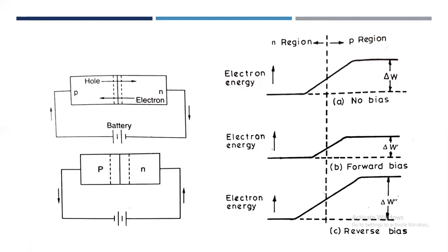For a given temperature, more of the majority carriers can now surmount this barrier energy than the higher barrier. At the same time, the number of intrinsic carriers that conduct the electricity in the opposite direction is unchanged, because the rate at which the intrinsic carriers are produced is determined by the breaking of covalent bonds, and it is not affected by the externally applied voltage. A large current thus flows, and applied voltage of this type is called forward biased. This first case, whatever we see in here, is called forward biased.